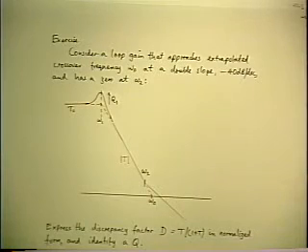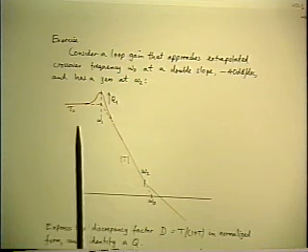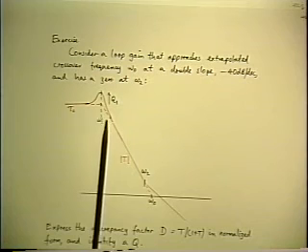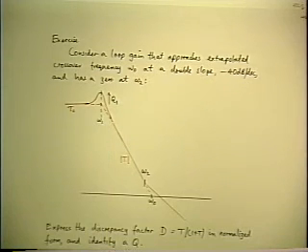Now I want to look at a related problem, and this one comes up specifically in the realm of switching power supplies. It's a good exercise anyway at this point. Here's a different shape of loop gain, starting from T0, and it has a second order corner. That is, it has a complex pair of poles, which might arise from a real LC filter, which is part of every switching power supply.